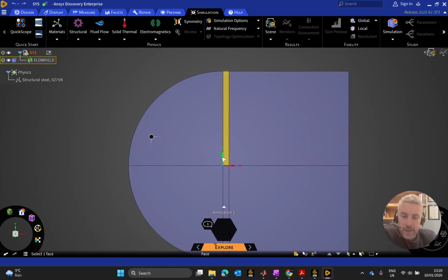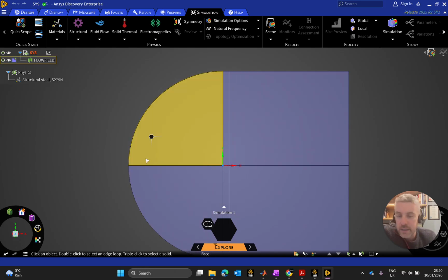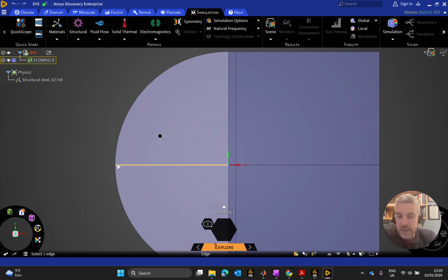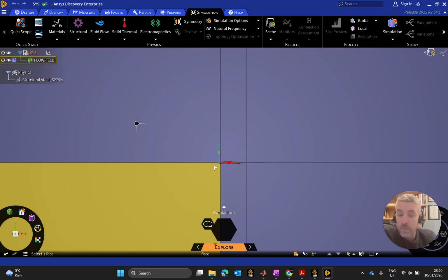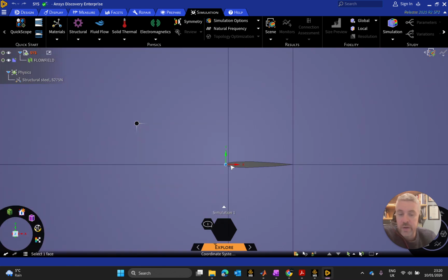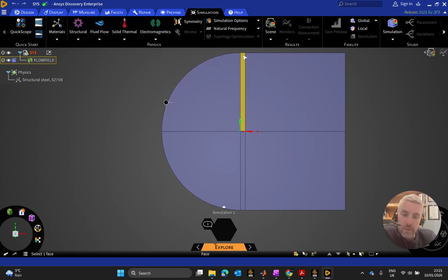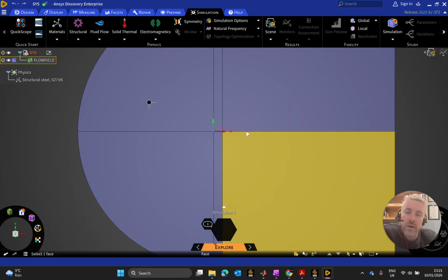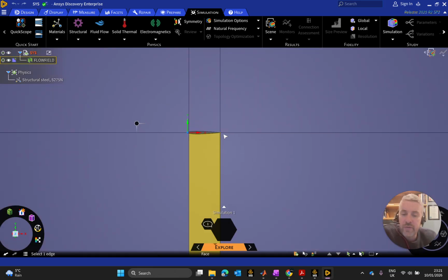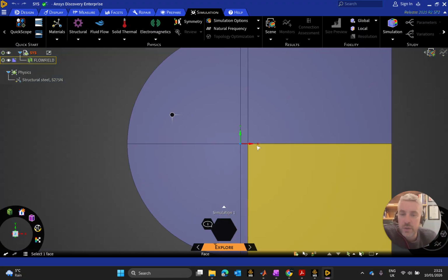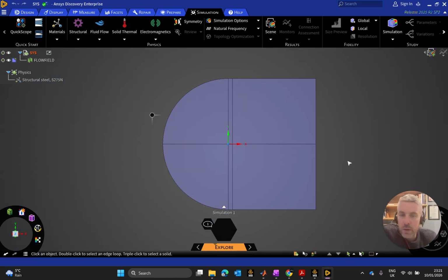The flow domain is a C-shaped domain here, and it has dimensions such that it extends 15 chord lengths out from the foremost point of the leading edge of the airfoil, 15 chord lengths above the airfoil, 15 chord lengths below the airfoil, and indeed 20 chord lengths from the aftmost point on the trailing edge of the airfoil. In this video we're going to move ahead and mesh these 6 regions.